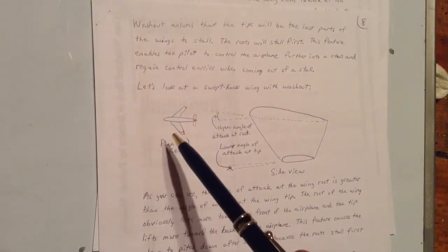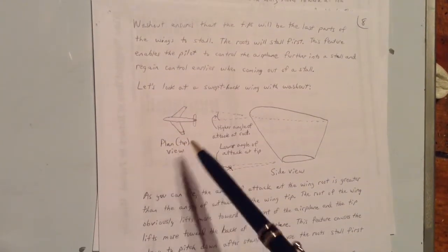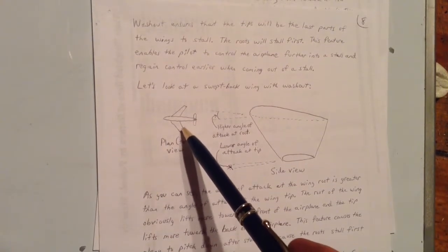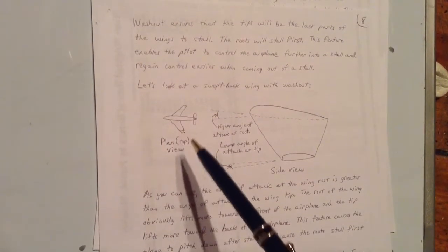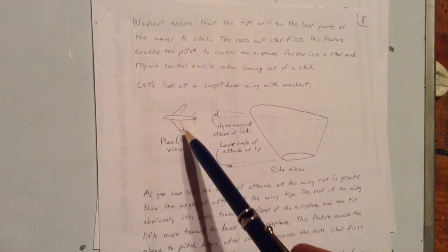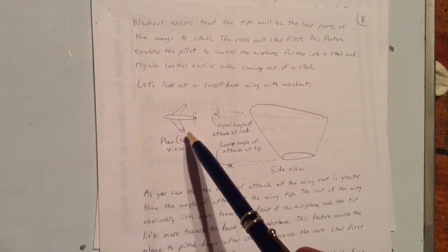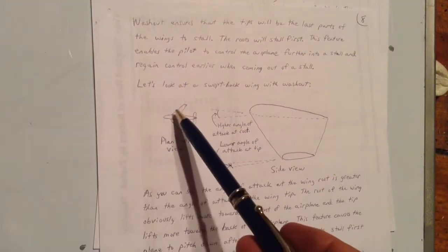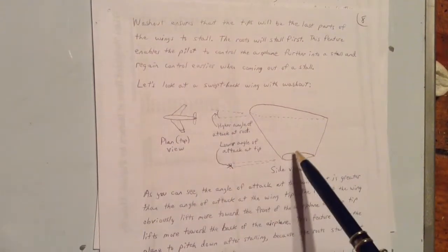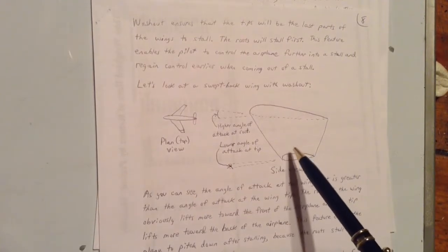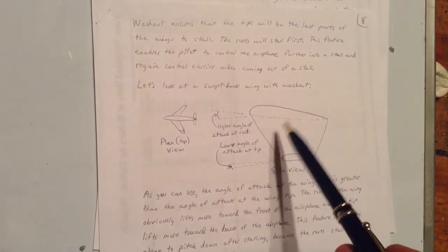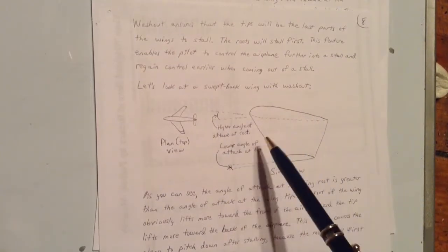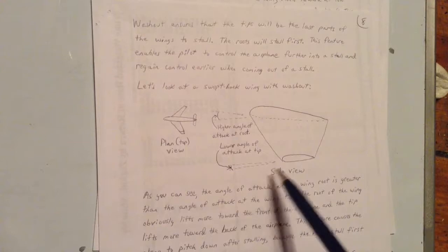So there's a jetliner I drew here. Had to make this wing a little longer, so I stuck that there and didn't have any white out for that little line there. But imagine this is a jetliner and you're looking at it from up above it in a helicopter. As you can see, the wings are swept back, plus they also have washout because the tips are pointed down a little compared to the roots. See, there's the higher angle of attack at the root. There's the lower angle of attack at the tip.